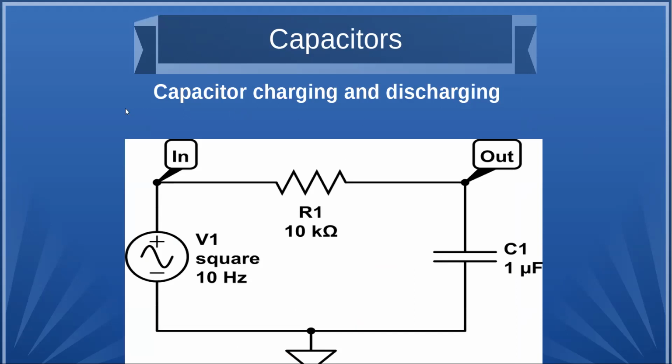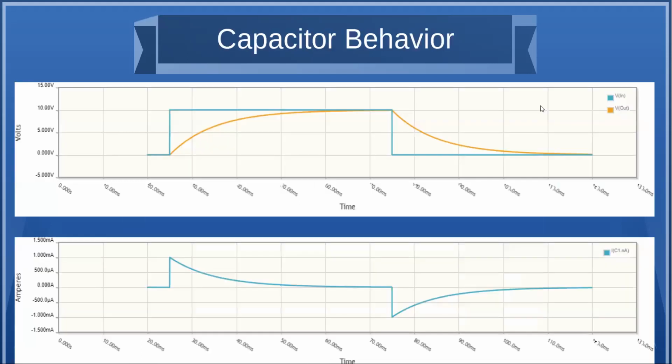Okay, here's a typical circuit. I'm going to show how we charge and discharge a capacitor. I've got a 10 hertz square wave coming in through this resistor just to limit the current a little bit, and a 1 microfarad capacitor. So when we simulate that,